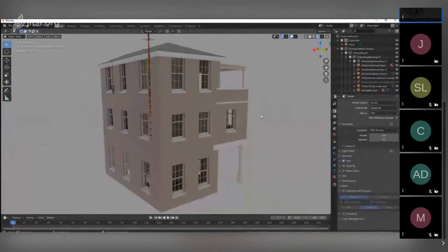Okay, so one of the main patterns that determine form turns out to be the light on two sides pattern. The way it's presented in the book is that all rooms should have double aspect, windows on more than one wall. But the pattern's a bit more subtle than that. It says that if a room's quite shallow, then windows on one wall are fine. But if it has a very low ceiling, then you need to have windows on more than two walls, and this kind of pattern generates nice spaces.